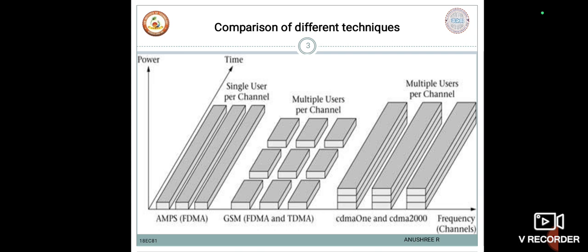CDMA 2000. CDMA 2000 is the term for 3G CDMA systems. CDMA 2000 was one of the 5 proposals the ITU approved for IMT-2000 third generation standards. As previously discussed in IS-95, CDMA 2000 is the wideband enhanced version of CDMA. It is backward compatible with TIA, also called EIA 95, and provides support for data services up to 2 megabits per second, multimedia services, and advanced radio technologies.